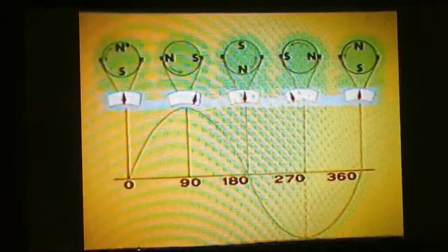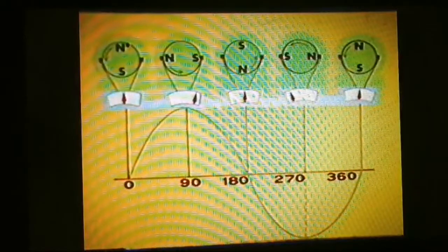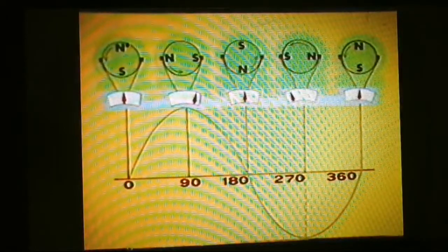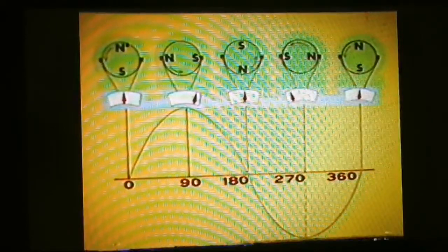Look at the voltage generated during one full revolution of the rotor by watching this meter. In the first half rotation, the voltage increases from 0 to peak when the rotor fields are closest to the coil, and then it goes back to 0 as the fields pass. As the opposite poles of the magnet rotate past the coil, voltage develops in the other direction and then returns to 0. This completes one full cycle.